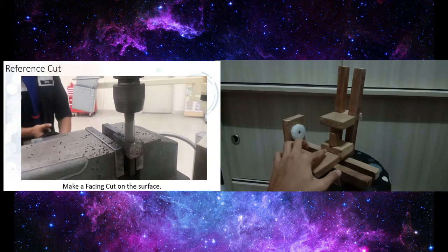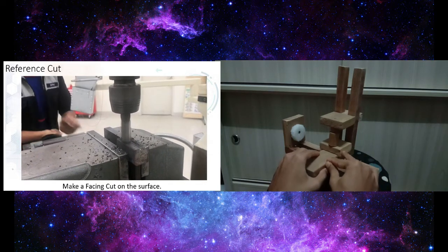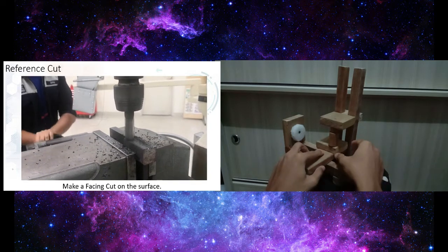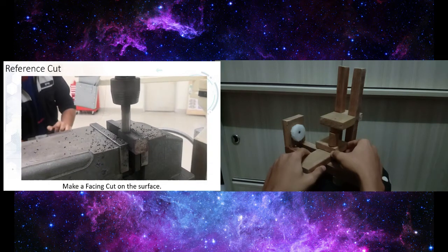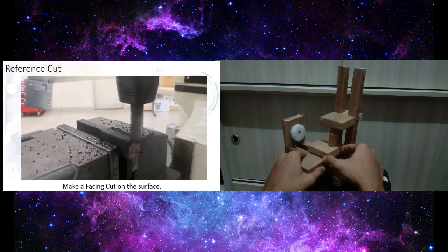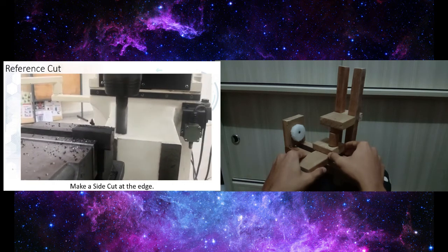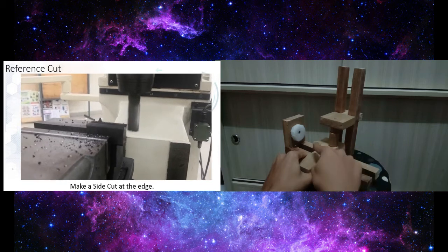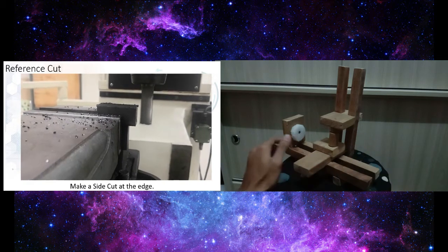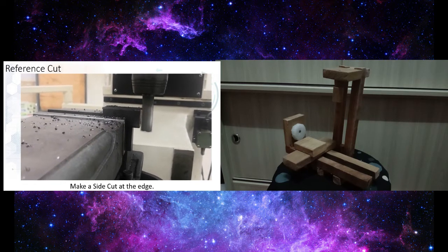At the end of the material, we will move the X axis to make the surface move to the other side. Then we will move the Y axis like this. So with that, all the surface will get the facing cut. We will do the same for this side and the other side until all the surface has the facing cut.